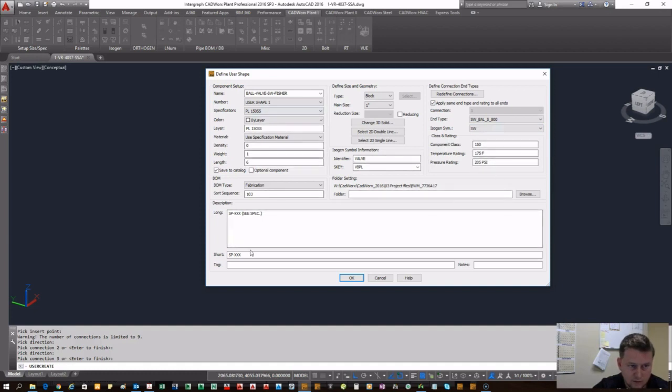It's good to check over everything, make sure you have your long and short descriptions correct. Everything right, your SKEY is correct, and if you have the proper information for weight and length. Now, whatever spec you're currently running, in this case I'm running my PL 150 stainless steel. Okay, that's where this data file is going to be associated with. So when you make this, you're basically copying that data file into this spec. Okay, make sure these match up with it. These should be pulled from the spec that you're currently running when you build the component. Okay, so click OK.